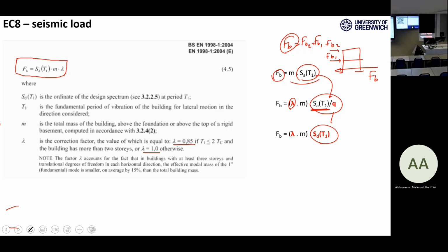So if you set Q equal to 1, it means that your structure will behave elastically during the earthquake and does not go into the nonlinear behavior, which is possible, but not optimized, it's too conservative somehow. You're not using the nonlinear capabilities and capacities of your structure.